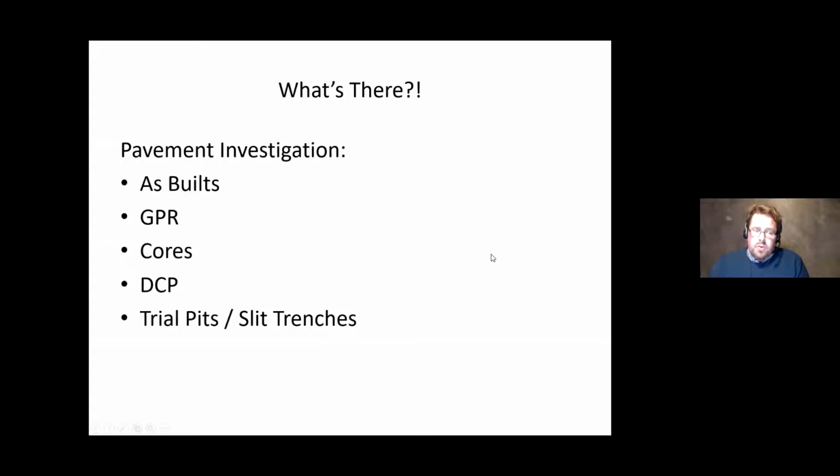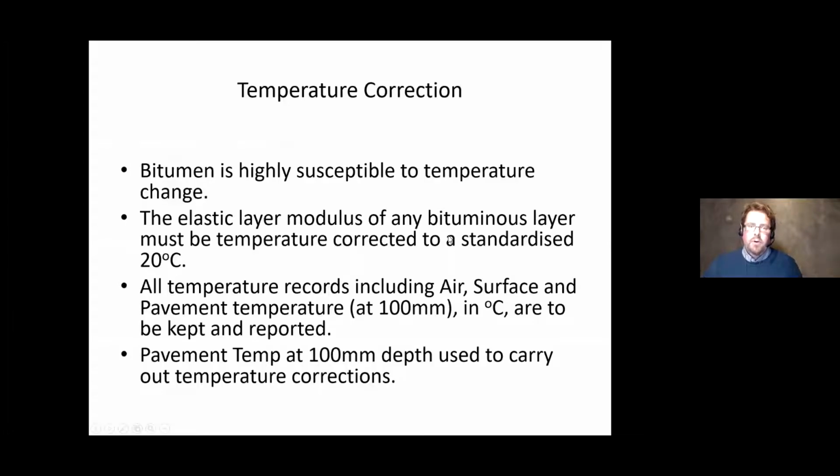Especially if you're working on national roads, expect to take at least 2 or 3 slit trenches, just to calibrate the rest of the data that you're getting, so that you're not sitting down with the TII and they say, okay, you've got cracking here, how deep does it go? And you don't know. Just take the time, hire a contractor with a digger, and take your slit trench. I know it's extremely invasive, but if you're doing the works anyway, you might as well be well informed.